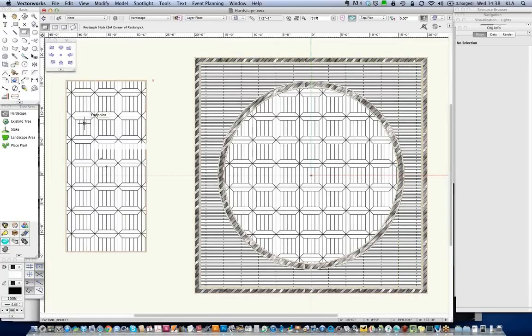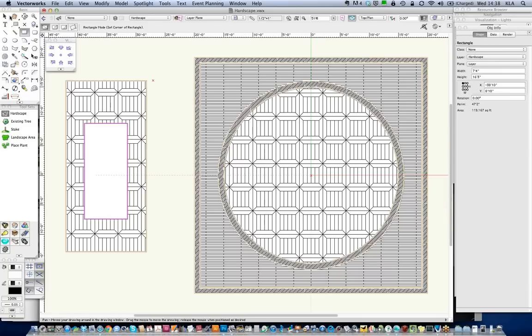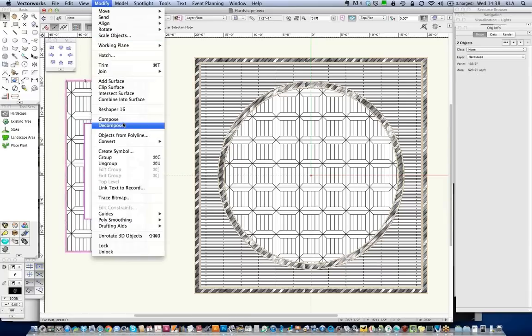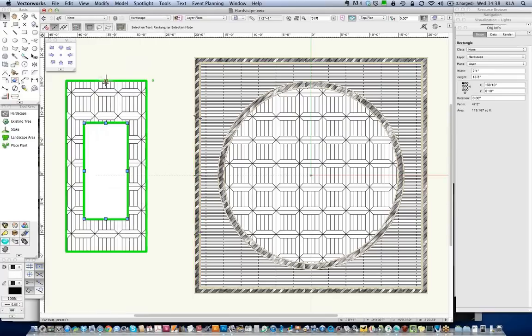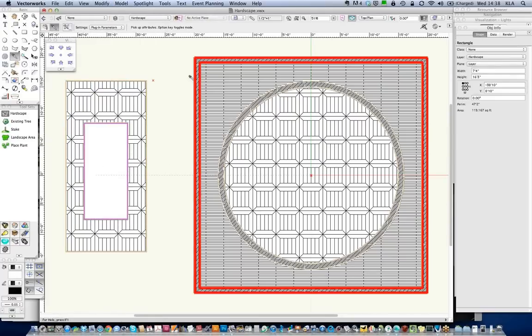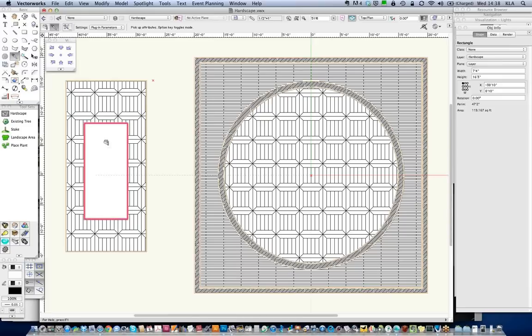In the plan view, I can also do a traditional flip. And then I can take the eyedropper again, and I'll grab that parquet border, click there. I'm going to go to the attributes palette and make all attributes by class.